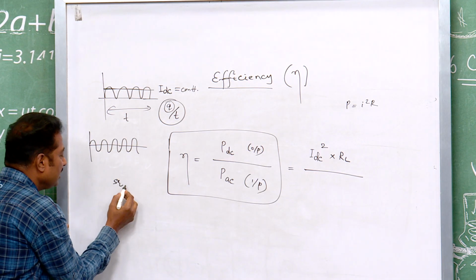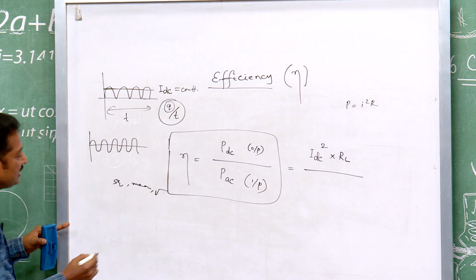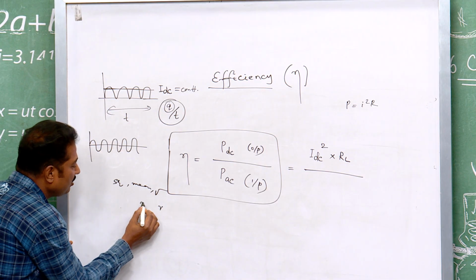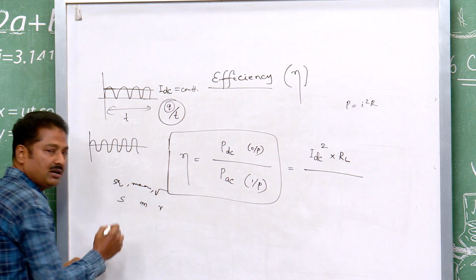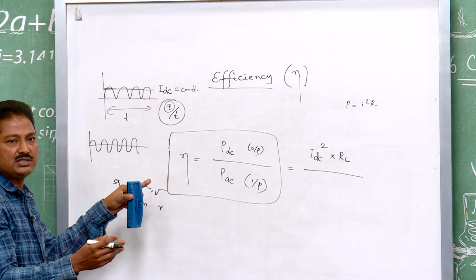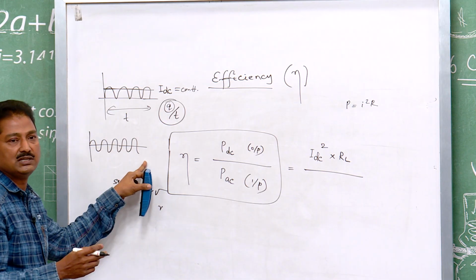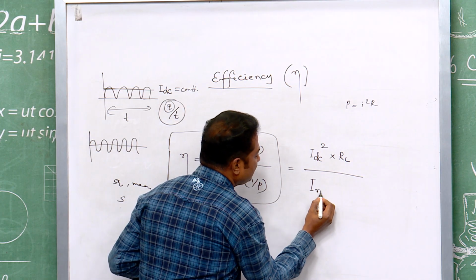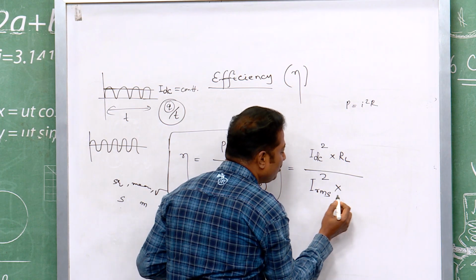First you square it, then you take the mean, then you take the root over. So, the name is RMS, root mean square, in reverse order. So, it is your RMS value which is the assumed constant value giving the same effect as the fluctuating signal. So, the AC it will be IRMS, that constant value is known as IRMS, and that square into,